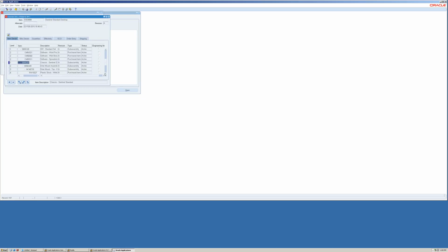This is the sequence of different items. Some items together form one particular item. All those items together form another item. Finally, we get the finished product. This is the drill down activity that should be mentioned in the bills of material. This means the structure of this parent item will be drilled down to the lowest level: what the raw materials are, what the components are, what the subassemblies are, and what subassemblies together form the finished product. That's what is indicated by the indented bills of material.